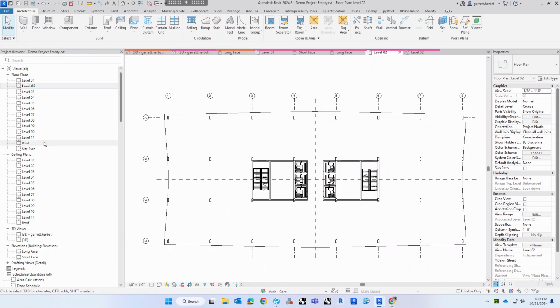So in reality, your walls are really only going to run between your floor and your ceiling and go up to the bottom side of your deck. Now, if you're modeling and you have something that is on top of each other all the way up through the building, you can't just have it extend.